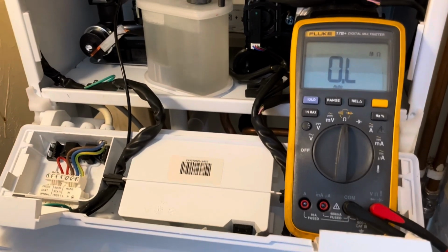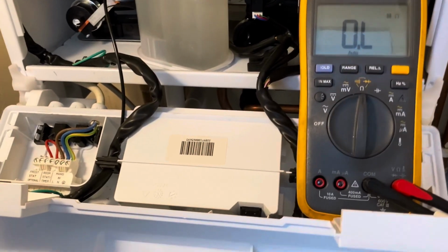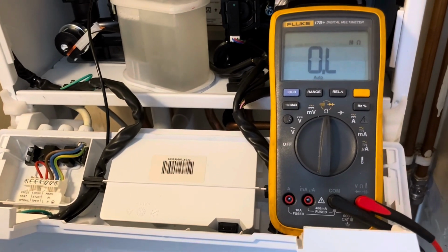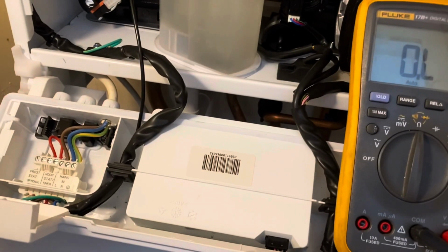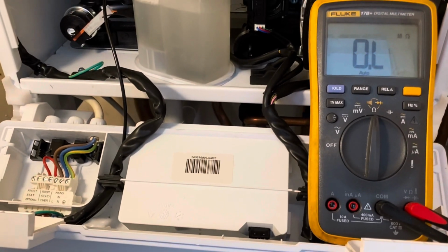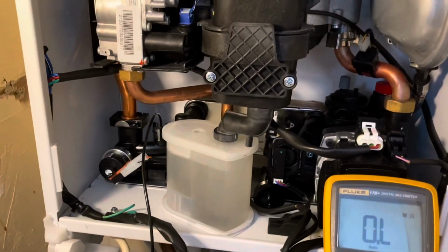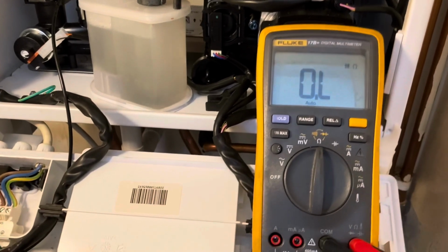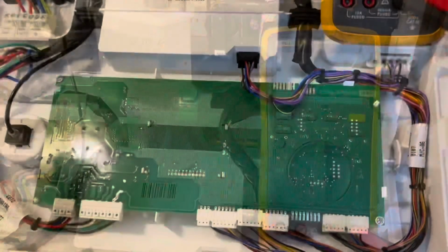So we've done a safety touch, incoming earth to the boiler, dead live dead, short circuit, polarity, resistance to earth, and earth continuity. They're the main electrical checks. And now I'll expose the circuit board and we'll do some dead testing on components, and I'll show you the reading from the gas valve where we worked out how many ohms the resistance should be through it. I'll set that up now.